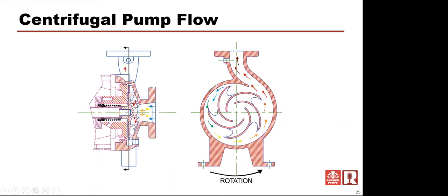So it's going to force this impeller not only to move radially, but also thrust load back and forth towards that low pressure side. So absolutely, the bearings would have a premature life, but the major complaint you're going to find, especially initially, is failing seals, because those seals in a bad installation or bad operating condition are going to fail prematurely.